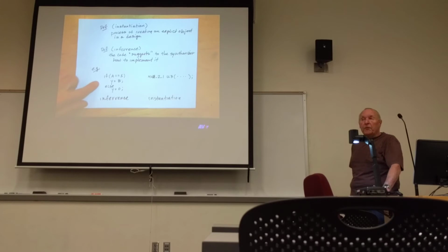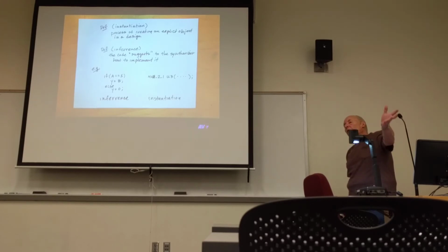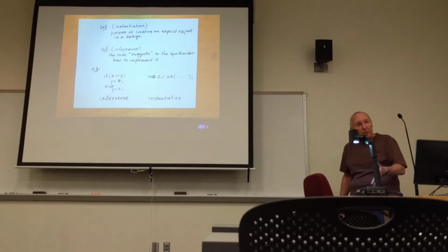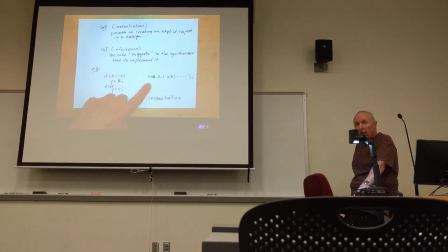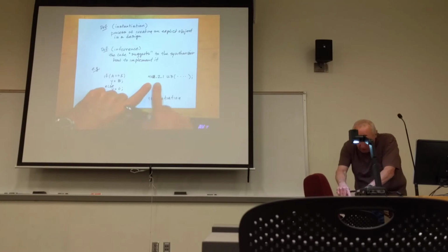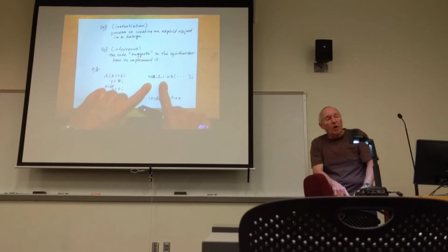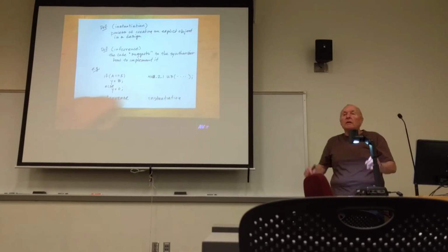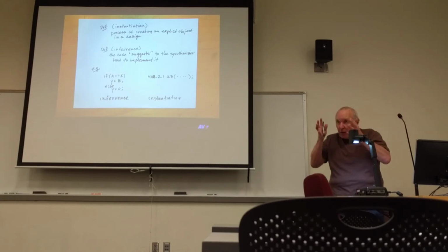If I write an if then else statement, I am inferring that the synthesizer used a multiplexer to implement. Here, I told the multiplexer specifically what I want, and I've got a module template called mux_2_1 with an associated port list. And that's specifically what I want put into the design.